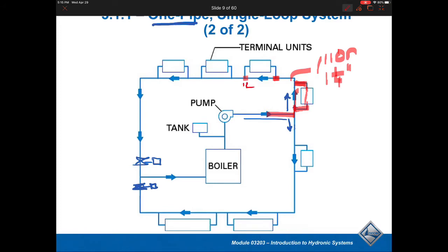I'm going to just point this out. In a monoflow tee, there's going to be a part of the tee that will be identified as having a ring. The rings will always go in between the terminal units. So that's something to watch for.